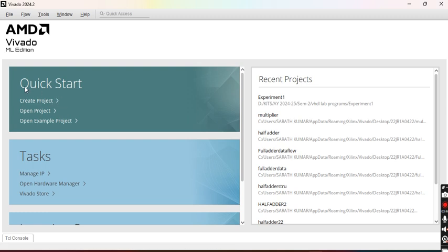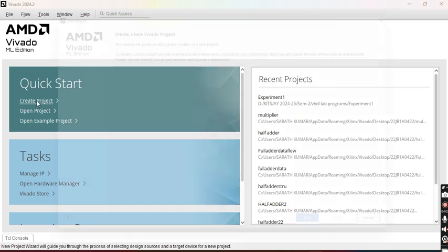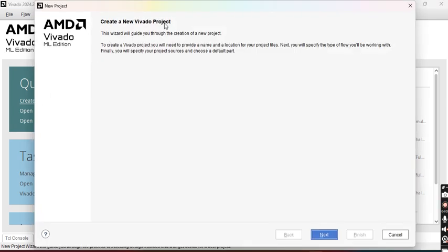Here in the quick start, you have a link to create a project. I request all the students to make a note of the points carefully by watching these videos so that you get the benefit of not wasting time in the lab. Click on create new project, then a create new Vivado project wizard will appear.